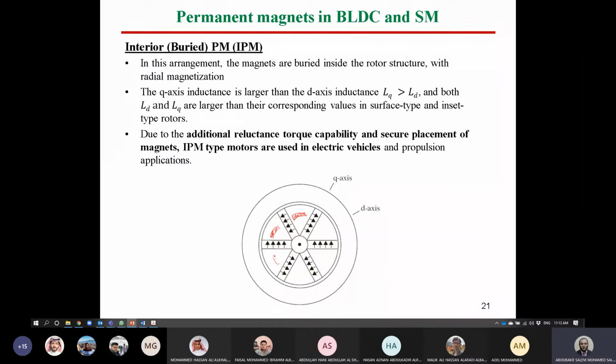Of course, guys, how we can select the proper shape is based on our design. All of these machines have to be firstly designed on programs using finite element method calculations, on programs like COMSOL, like ANSYS, any multi-physics programs that can give the performance at different configurations, and then by using optimization techniques, select the best way to insert the magnets inside the rotor. Okay, guys, to reach the best design.